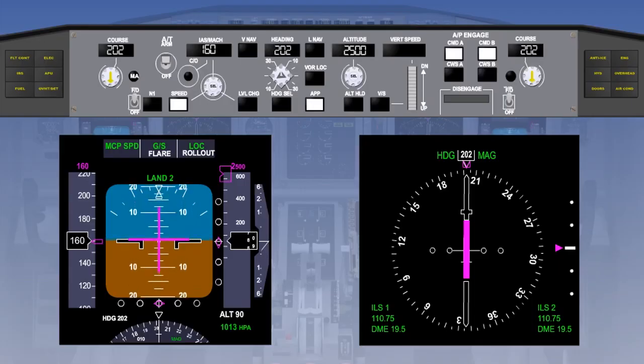At 50 feet radio altitude, or 45 feet wheel height above the ground, flare mode is engaged, and the glide slope signal is disconnected. The rate of descent is reduced to approximately 2 feet per second. This is achieved by the radio altimeter controlling the flare to reduce the rate of reduction of the radio altitude.